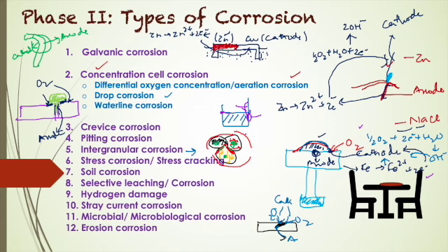This results from the development of differential cells at these points, leading to corrosion. Many metals with a corrosive medium moving at high velocities can suffer erosion corrosion. These media can be gases, aqueous solutions, or liquid metals. For example, hot gases may oxidize a metal and then, at high velocity, blow off the protective scale around the metal. So this falls under the category of erosion corrosion. On the other hand, in desert areas, high wind velocity can cause corrosion of the metal surface.